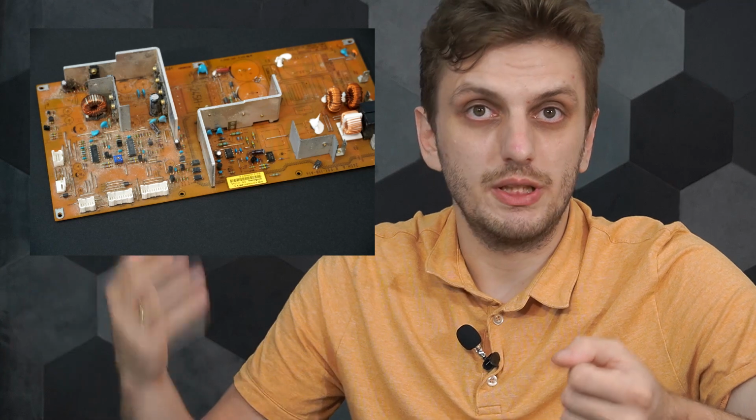You can go one step further by adding vertical plates on your board to protect some sensitive areas from some noisy areas, and this sort of plate can have dual function, to be used on the one side as a heatsink for some sort of power transistor, but if they're properly grounded, then they will also provide a certain level of shielding.